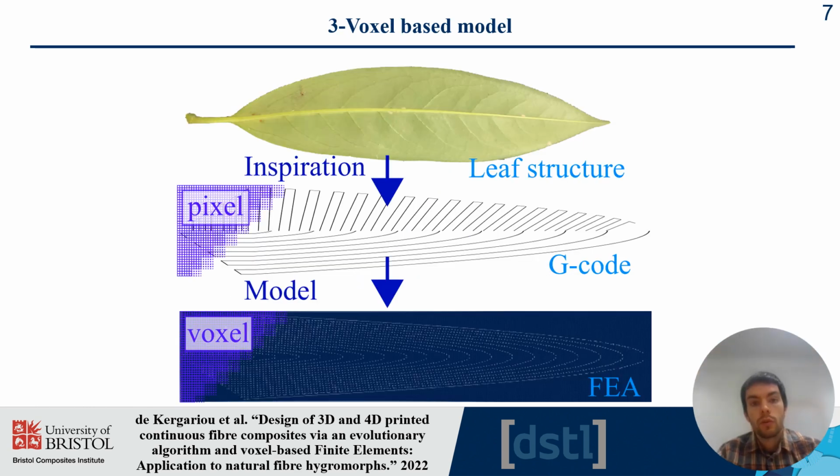We wanted our structures to be anchored in a specific framework, and this framework encompasses the structures which are produced with a continuous filament which cannot be cut. They also need to be usable in order to fasten optimization. So basically we want to work with a discrete number of printing parameters which could be used as input in an optimization system, and we want to be able to play easily with these parameters in order to control the entire printing path of the structures.